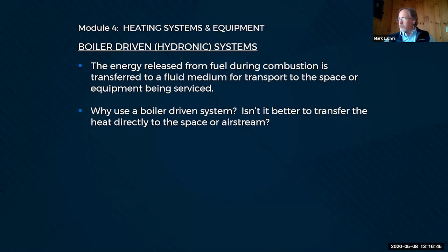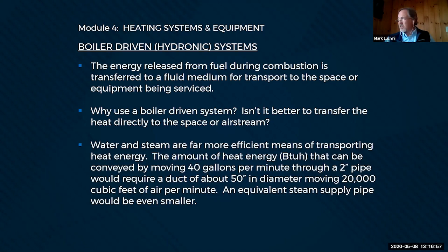Why would we use a boiler-driven system? Why wouldn't we just want to transmit the heat directly to the space that we're trying to heat, or directly to the airstream that serves that space? Well, the answer is simple. Water and steam are very efficient means of transporting heat energy compared to air. So I can move the same amount of heat energy in a 2-inch pipe that would take me a 50-inch duct to do. So when space is at a premium, it becomes pretty obvious why we use water and steam to move energy around.